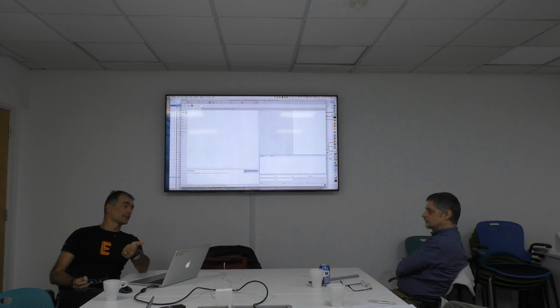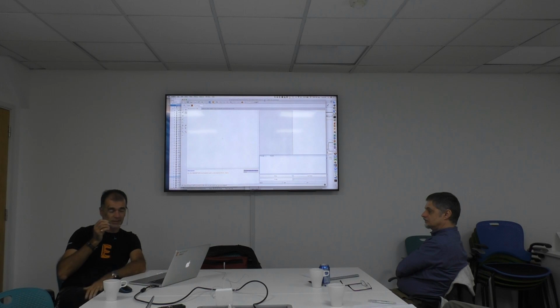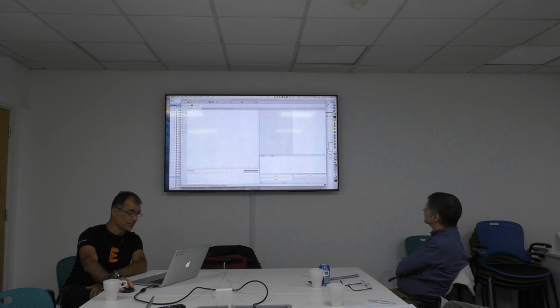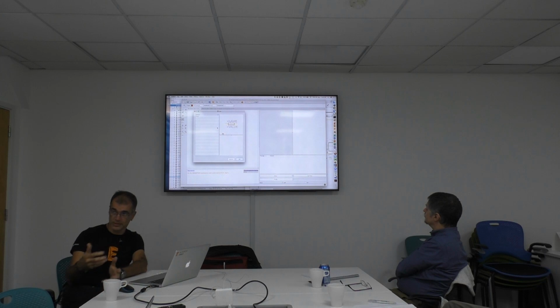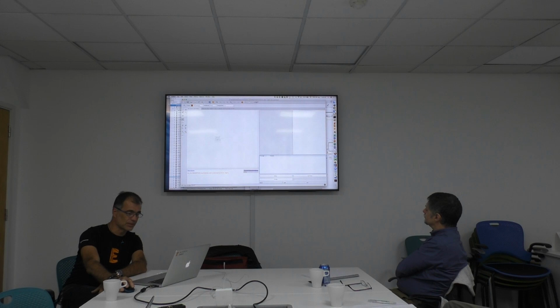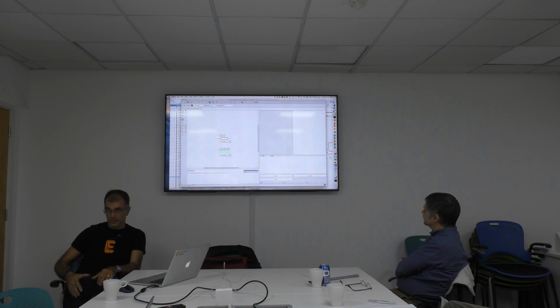Now I have to add my symbol. You do it the same way as you do it in the schematic. I have the add command. And what I see now is, in the library, there's only one symbol we have to create. I select this one, say okay, here it is. And I can place it. That's it. There's the next symbol on the mouse cursor.